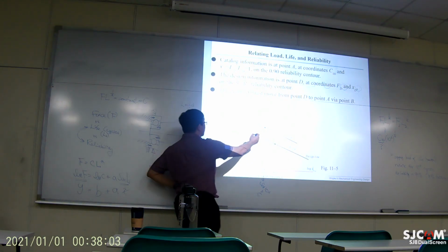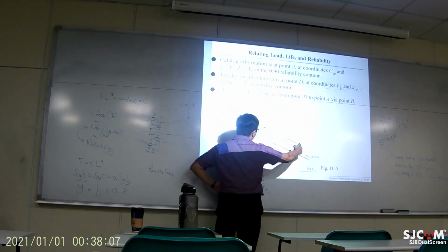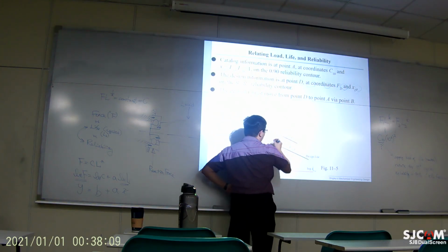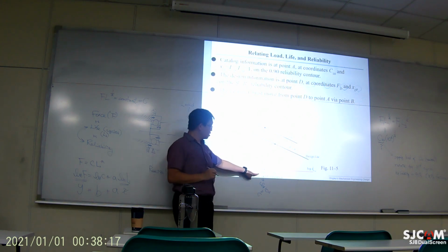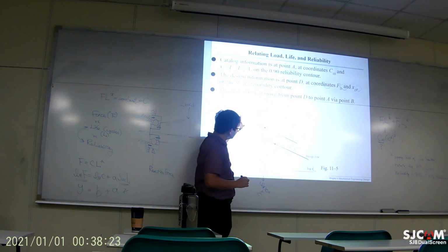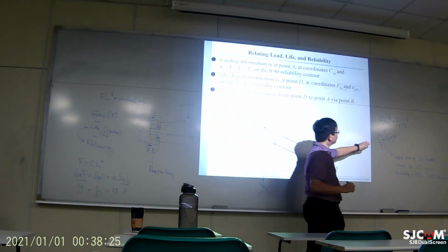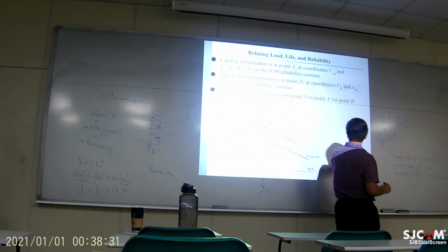So it ends up with some point right here, and this line represents reliability of 90%, because this comes from the load of C10 at cycles of 10 to the power of 6, and on this particular line you will be matching this log-log linear relationship.